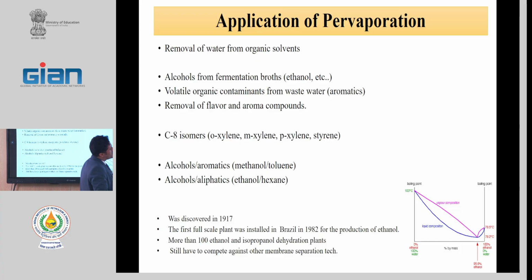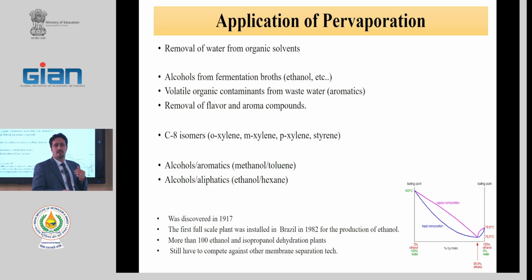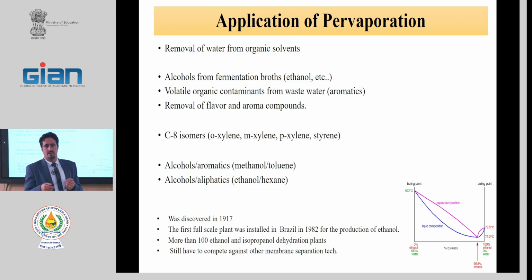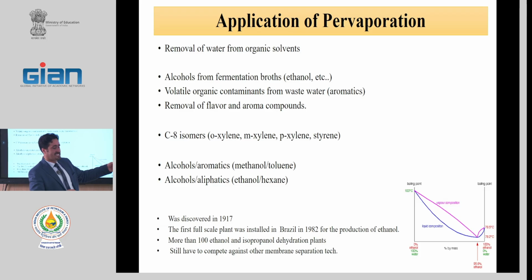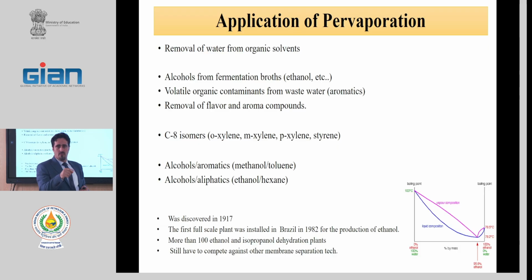For resolving this problem, industry 30 years ago added benzene or toluene to this 96% and redistilled. By addition of benzene or toluene, the azeotrope is destroyed, and with redistillation, absolute ethanol, 100% ethanol, is produced. That is very expensive.